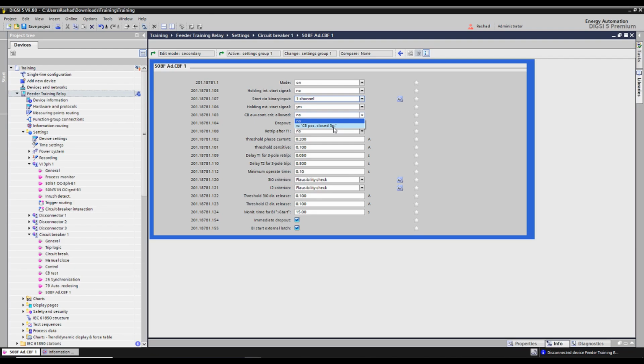What is the difference between the two when I receive an initiation to check whether the breaker is still closed or has opened? How do I know? Well, for the current mode, you are supposed to measure the current. Okay, in the low current mode, for example, I received an oil low level alert on the transformer. It is not necessarily that the transformer is energized from both sides. It could be that its upstream is closed and the downstream is open, and therefore there is no load on the transformer and no current is actually passing through.